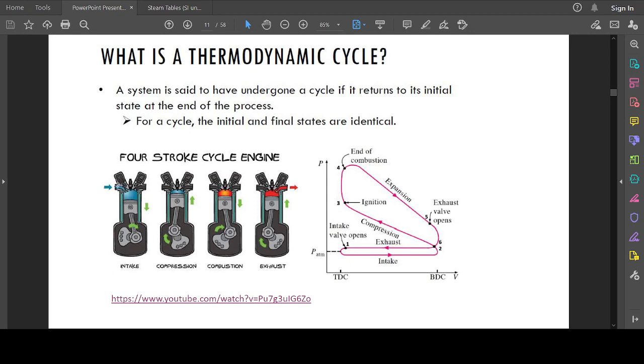Here, at the intake end of the engine, a fuel injector injects fuel into the air intake. Now the air and the fuel mix as a kind of vapor, and it goes into this chamber. Due to the motion of the piston, the rod, and the crankshaft, the chamber provides enough space to draw in the mixture of air and fuel. That is also helped by the opening of this valve here, the intake valve.